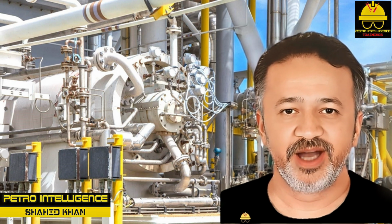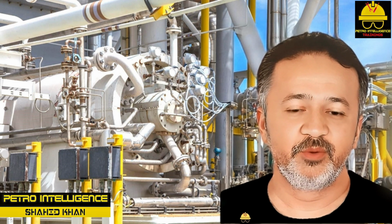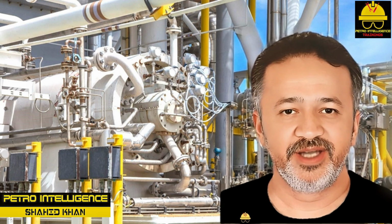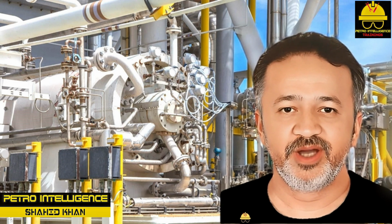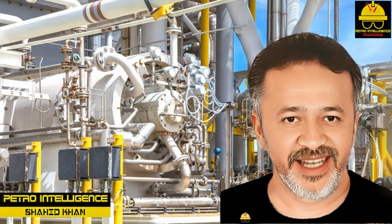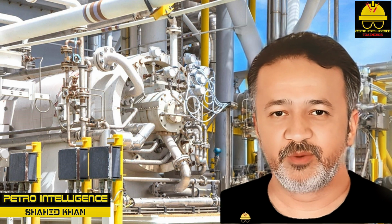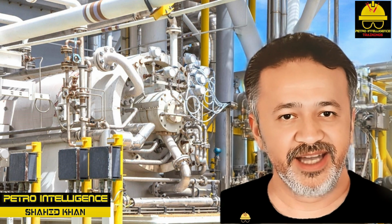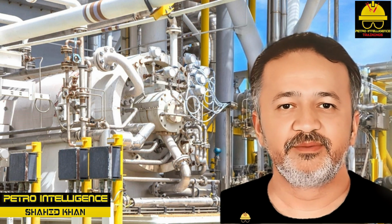For this reason, the diaphragm compressor is ideal for applications that involve explosive and toxic gases. Membranes are designed to be durable and tough and able to withstand high temperatures and a variety of conditions. Diaphragm compressors can generate very high pressures and are used to compress hydrogen, hydrogen chloride, carbon monoxide, and compressed natural gas. Diaphragm compressors come in 1, 2, 3, or more stages. Each stage requires the use of one diaphragm.